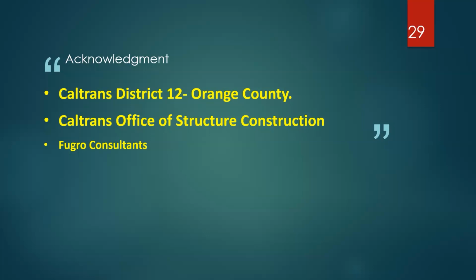You said that the piles were subjected to pile driving analysis during installation. Was static load testing performed as well to calibrate the PDA data against the static load test results, or did you purely rely on the PDA data? Another great question, Gerald. As much as I would have loved to have a pile load test on this project, the Caltrans requirement is that if you have anything more than a certain diameter of pile and a certain amount of load, then you require a pile load test. And in this case, the diameter was only 24 inches, which requires only PDA.